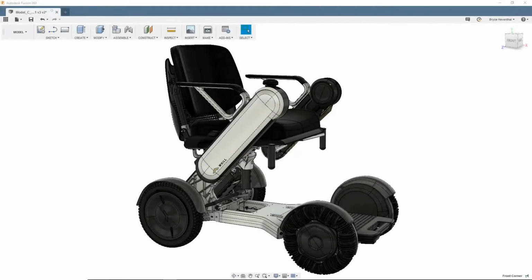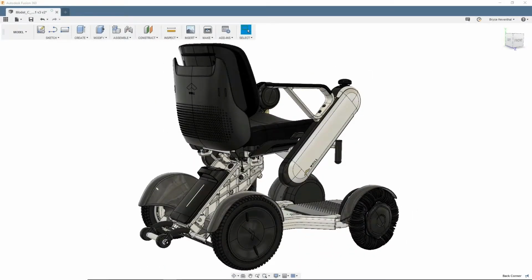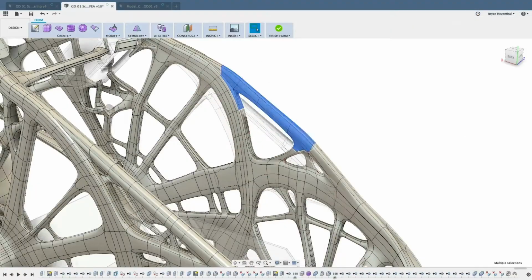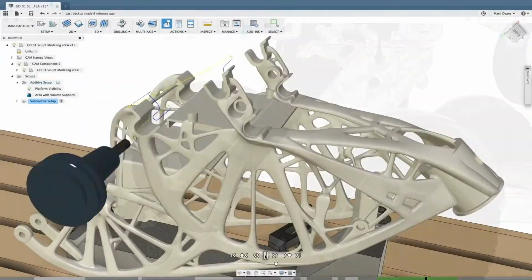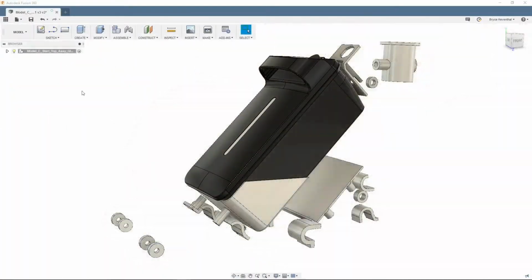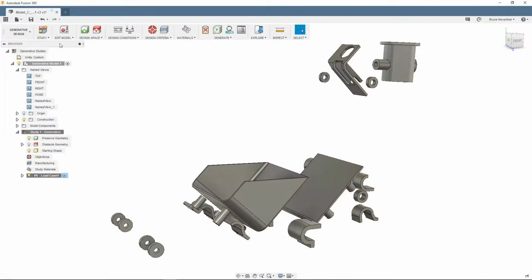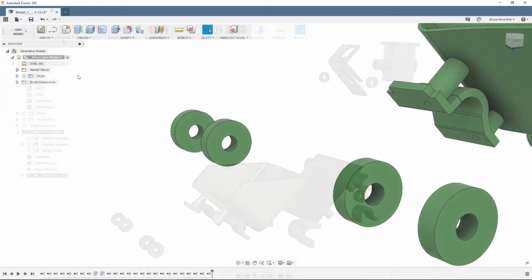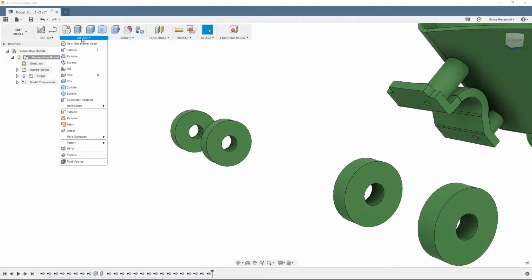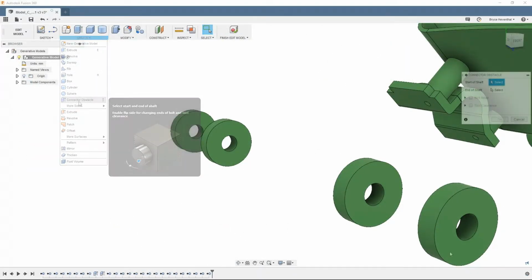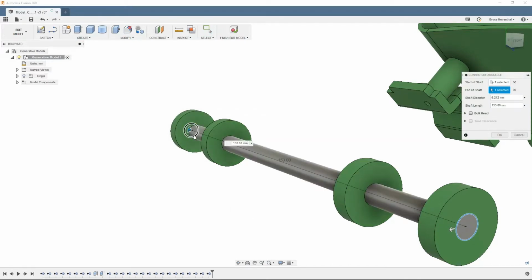Harnessing Fusion 360's generative workspace might sound like a challenge. After all, its ability to connect design, simulation, and manufacturing into one is like nothing before. But it starts simply, with framing the problem. Using the Edit Model workspace, designers can simplify geometry, remove unnecessary parts, and create new bodies specific to the generative setup, such as fasteners and tool clearances.